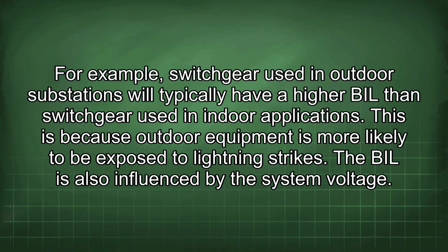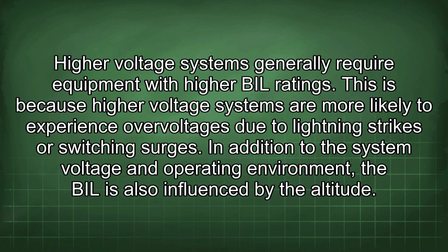The BIL is also influenced by the system voltage. Higher voltage systems generally require equipment with higher BIL ratings. This is because higher voltage systems are more likely to experience overvoltages due to lightning strikes or switching surges.